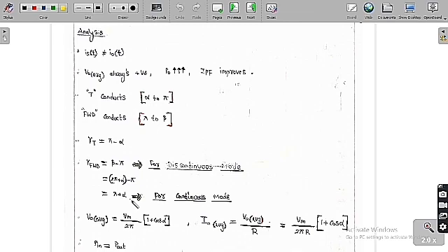So listen carefully. Beta minus pi is the conduction angle of the freewheeling diode for discontinuous conduction mode. Whereas for continuous conduction mode, from 0 to alpha the freewheeling diode is going to conduct, and again from pi to 2 pi it is going to conduct. So the overall value is pi plus alpha. So for pi plus alpha the freewheeling diode is going to conduct for continuous conduction mode. And for both these cases, the conduction angle of the thyristor is the same, which is pi minus alpha.